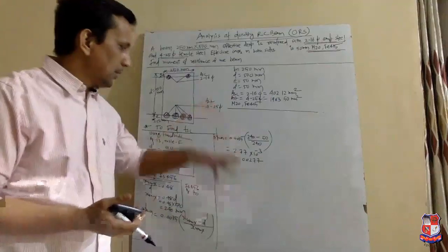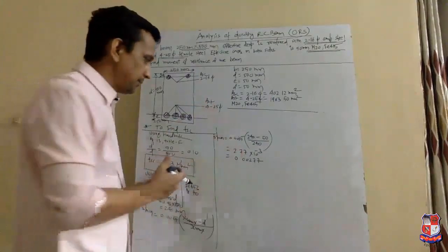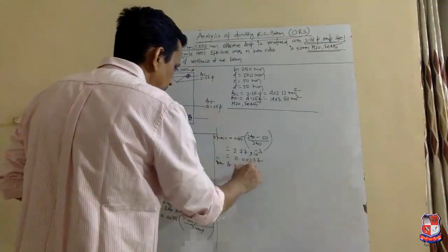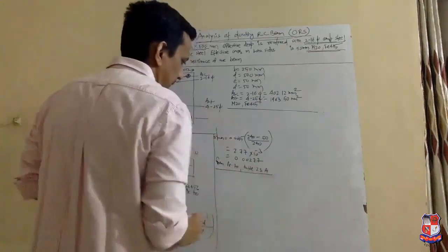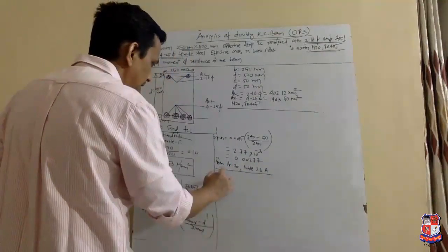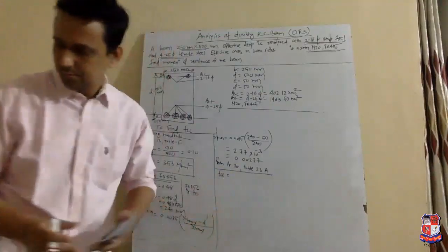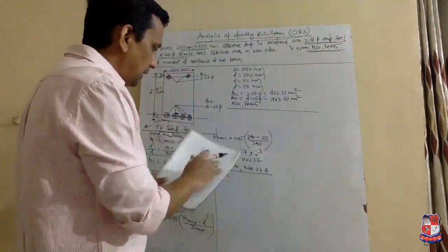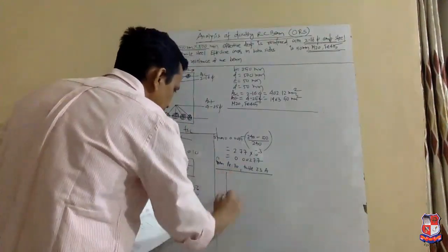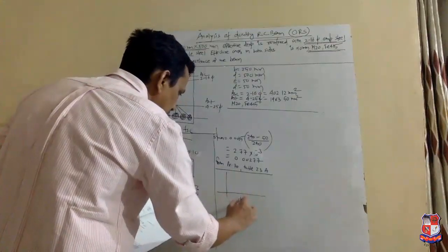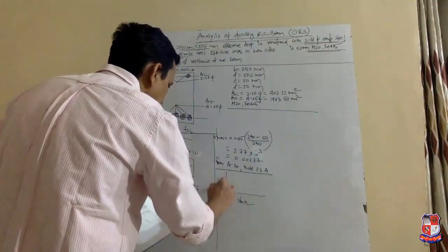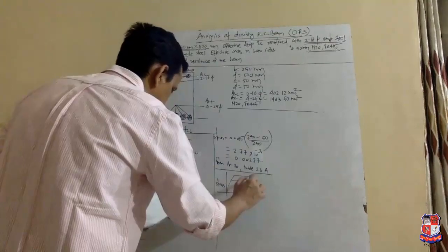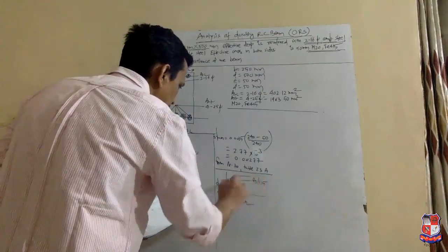Now, once we find the strain value, we have to find the stress from IS 456 page number 70. So from page number 70, table 23A, right? We get the FSC value. On page number 70, let me explain again: the horizontal value is strain and the vertical value is stress. They have given this and we need to take values from this line.